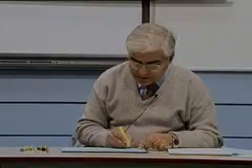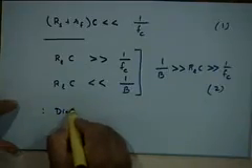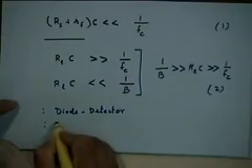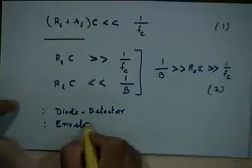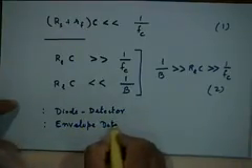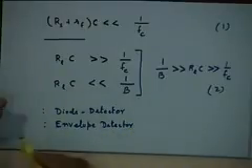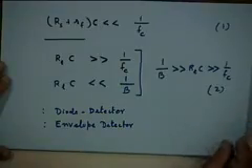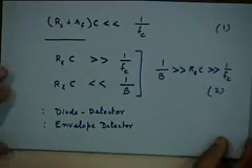Okay, so that is what the envelope detector is all about. This is what we call the diode detector. It has various names. We also call it the envelope detector. And as you can see, just with these three components, a diode, a resistance of a sufficiently large value, and a capacitance, we can build a very simple demodulator, right? And that's what most of your AM receivers do, that you use in your homes or whatever.